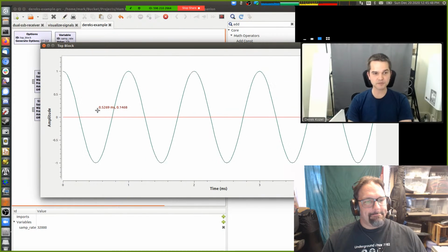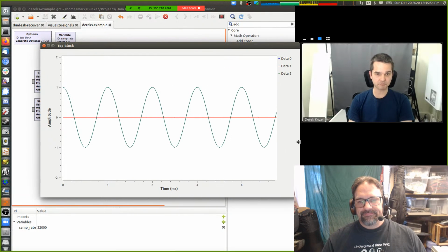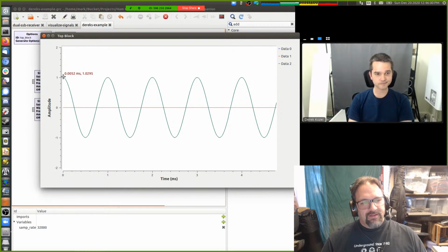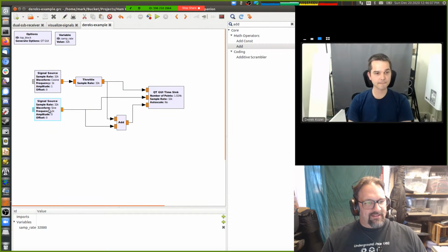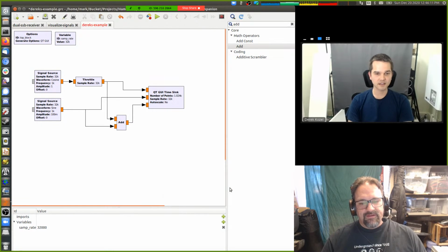Because you didn't have any Q component here, any quadrature signal, the result is a 0 phase shift, 0 amplitude change between the two. So unsurprisingly, the result is exactly a cosine, because you've added a cosine to 0. So let's add just a little bit of sine.